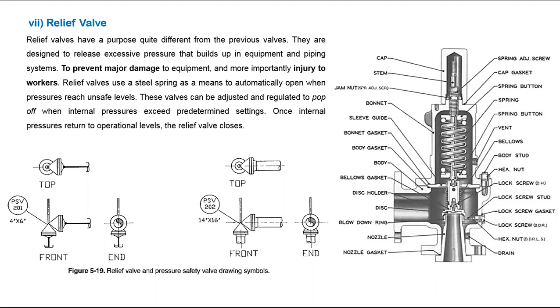In some projects, we maintain a maximum of 2 bar pressure only. When you are not going to use any special shower arrangement, you can maintain 2 bar pressure. When you are using a special type of rain shower in our project, you have to maintain up to 4 bar pressure for operating the rain shower or special type of shower. For that special type of shower only, we maintain 4 bar pressure. Otherwise, you can do 2 bar pressure. That's all.